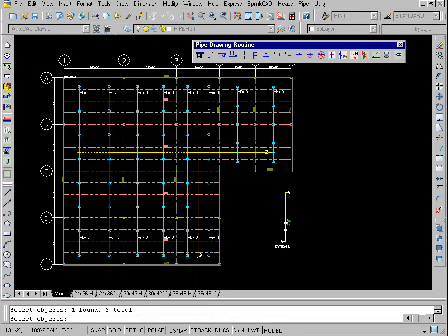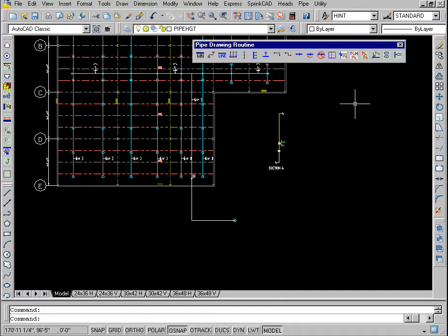Make sure to pick the pipes for insertions. If the elevation symbols are not inserted precisely on a pipe, errors will result. You can edit the elevation values by double-clicking on the tag. Start the command again and enter -4 feet as the elevation. Place elevation symbols on each of the 2 underground pipe pieces.